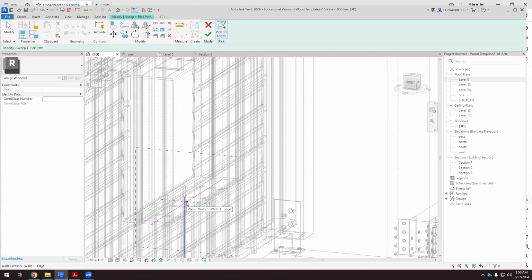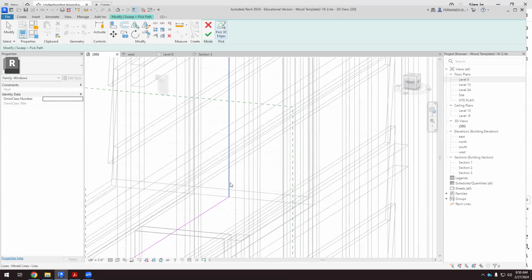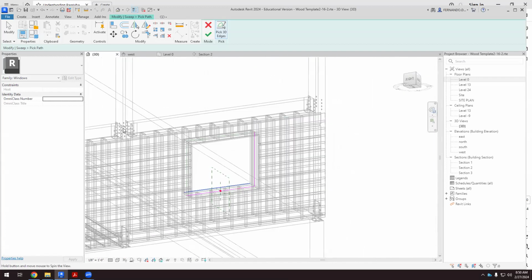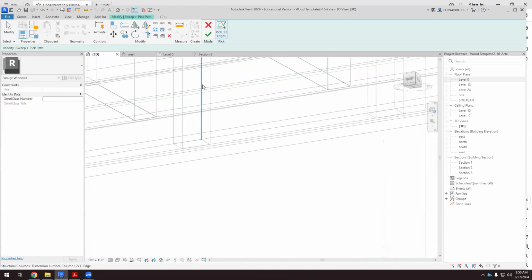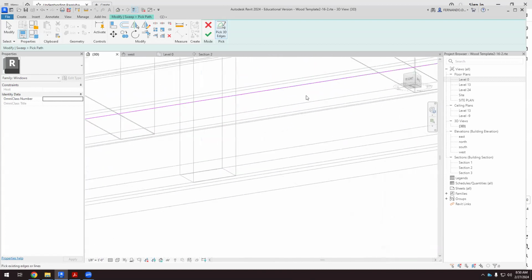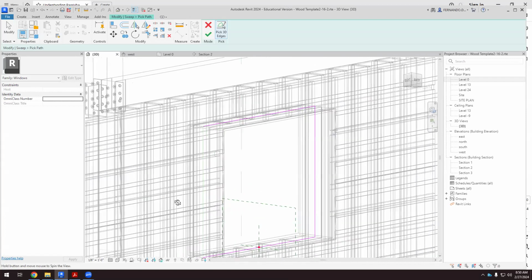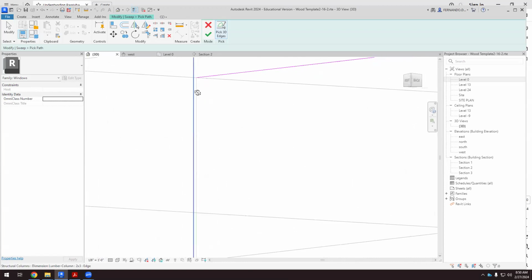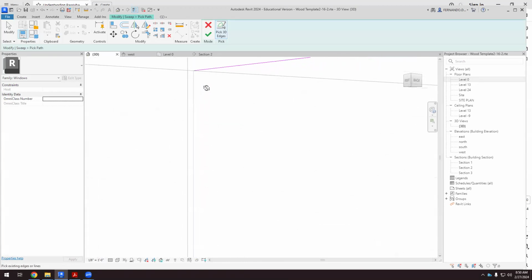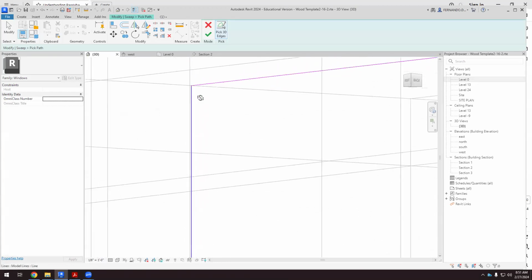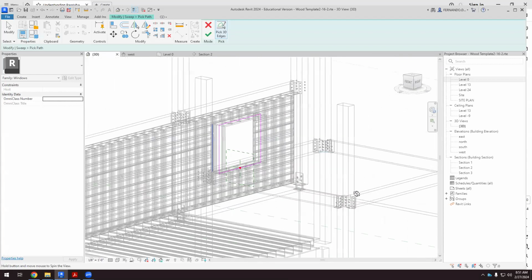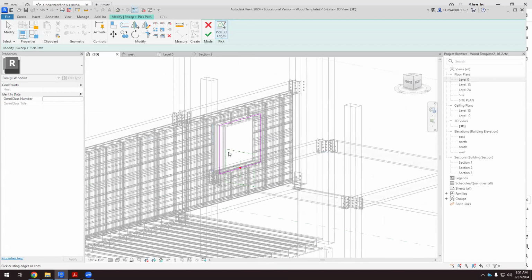We have this starting point here, and then we have to keep picking the green line that we have here in this frame. Be careful because if there are 2 lines very close to each other, we have to pick the green. So the path has to be a closed loop. Okay, so if it's not a closed loop, well, it will work, but it won't do what we want it to do. Okay.